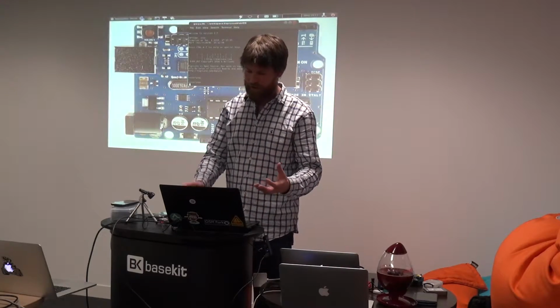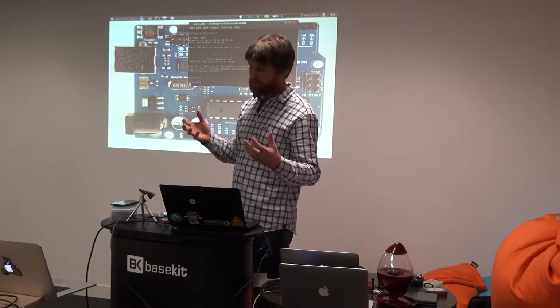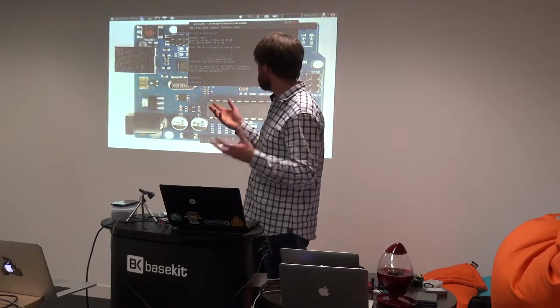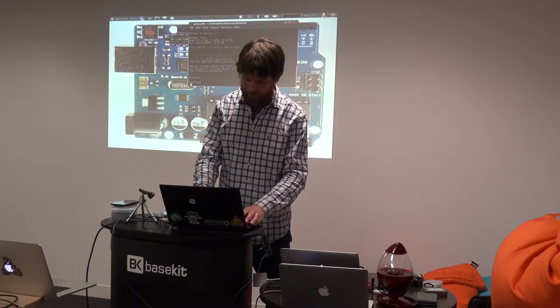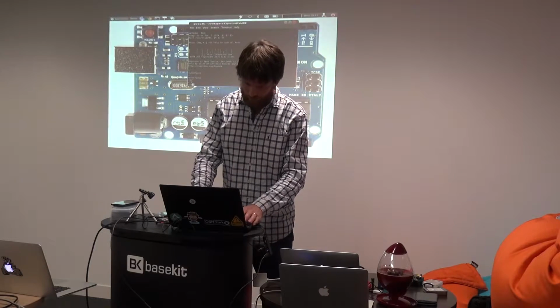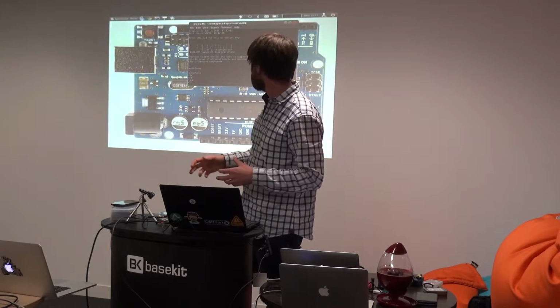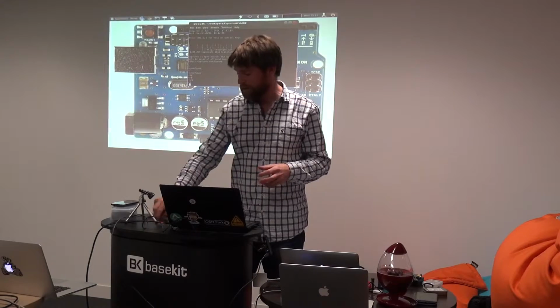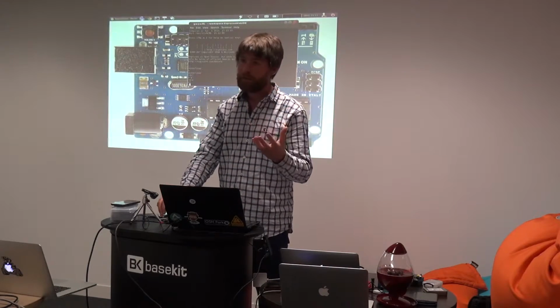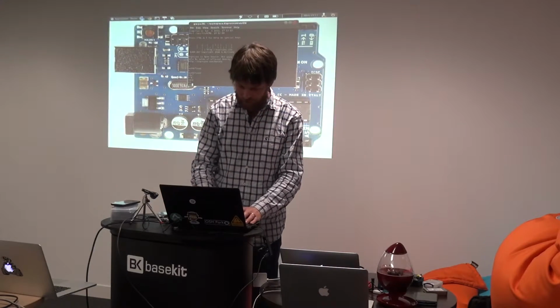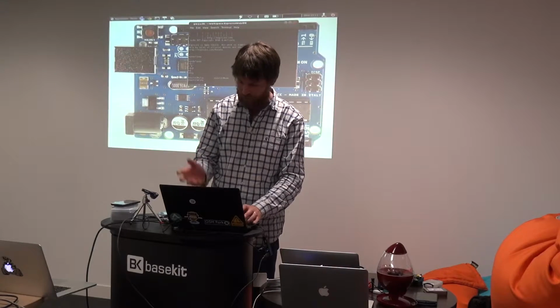So here you've got a connection to the device itself. I can type stuff in, and it'll be executed, and the result will be returned, actually running on here. I can issue it commands that are Arduino style. So if I say digitalWrite, it's got a kind of command completion in it.